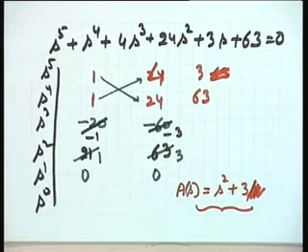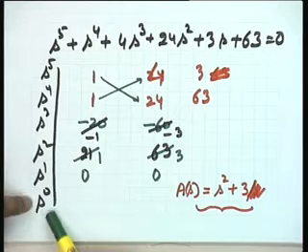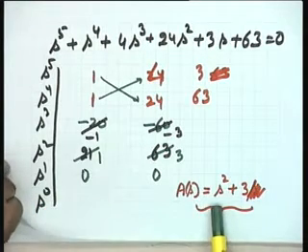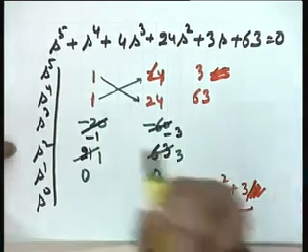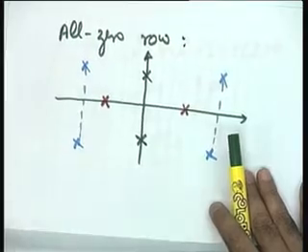See his question please: is an S0 row an all 0 row? Let us see whether it is true or not. Can anyone answer? Probably the answer lies in the discussion I have given. If this is the row, in that case one of these possibilities is not possible, because the so-called auxiliary polynomial will be first order, which will give rise to a single root, and a single root does not give rise to an all 0 row.